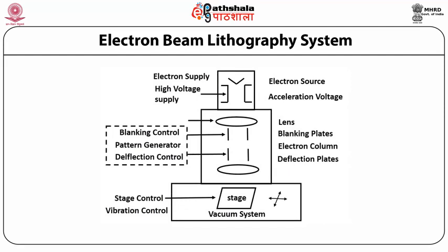Electron beam lithography systems can be classified according to both the beam shape and beam deflection. Earlier systems scanned Gaussian shaped beams in a raster fashion. Nowadays, systems use shaped beams which may be deflected to various positions in the writing field, also known as vector scan.